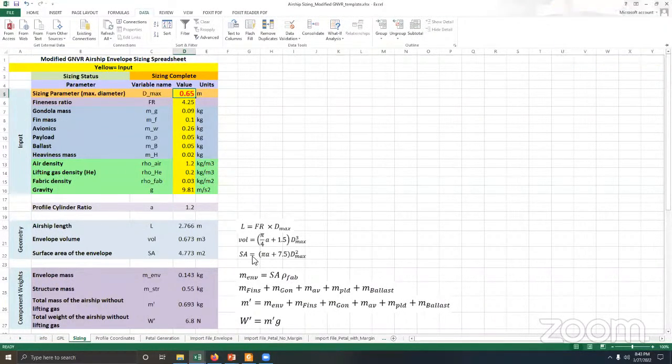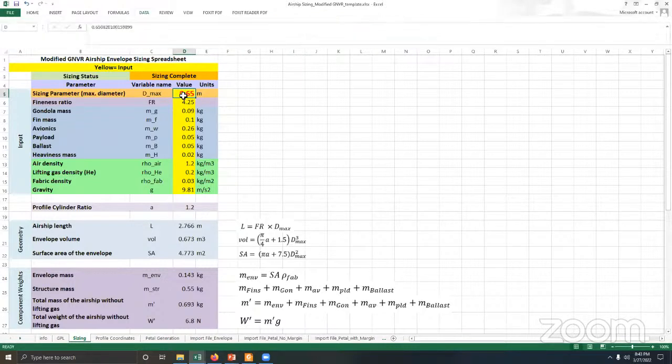One more thing I want to add: when you do Goal Seek, remember the cell that you are changing, in this case D5, the Dmax, cannot have an equation. It should only have a number, because Excel cannot play with an equation to change the answer.